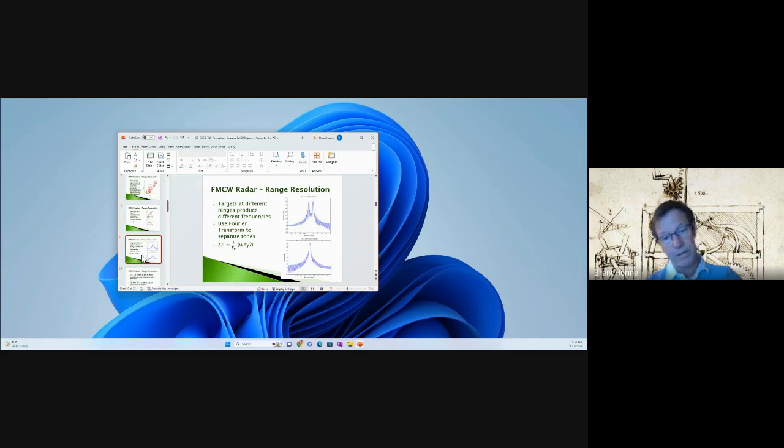Then we go through the Fourier transform, and now suddenly, magically, we have potentially infinite frequency resolution in the spectral domain, but no time resolution, right? If our signal varies in time, we don't perceive that in the spectrum.